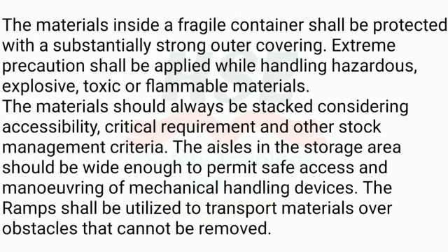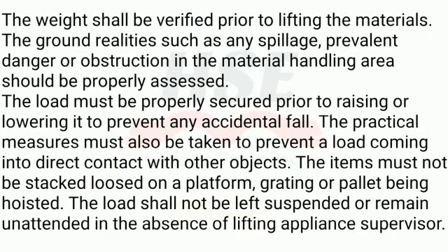The materials should always be stacked considering accessibility, critical requirement and other stock management criteria. The aisles in the storage area should be wide enough to permit safe access and maneuvering of mechanical handling devices. The ramps shall be utilized to transport materials over obstacles that cannot be removed. The weight shall be verified prior to lifting the materials.